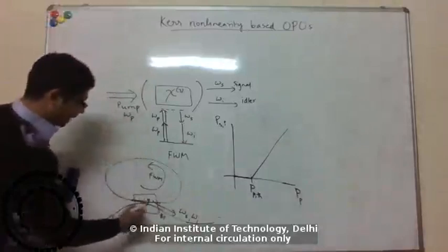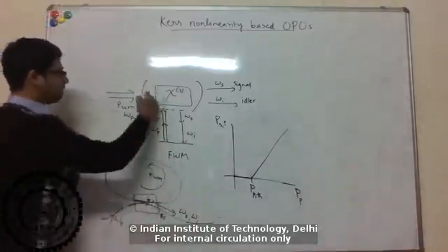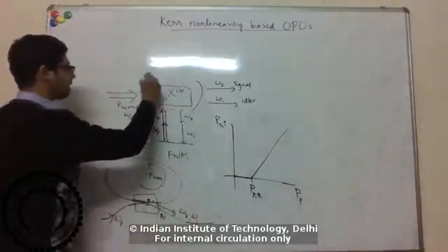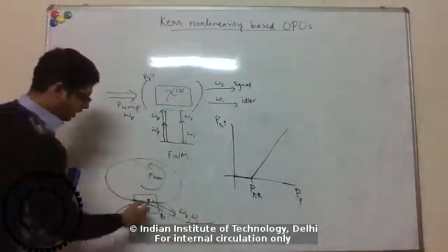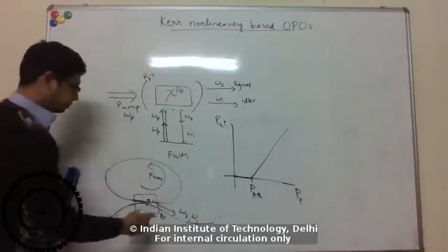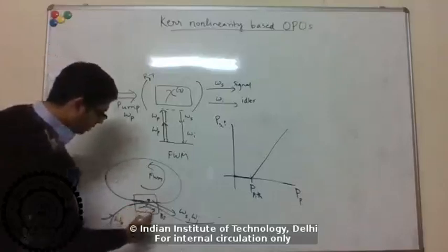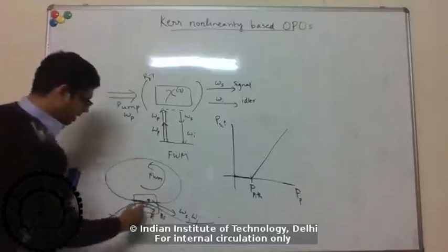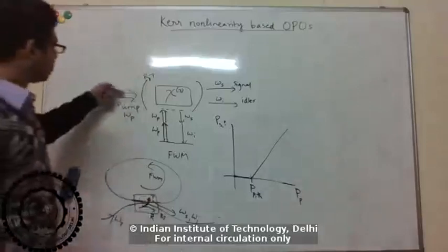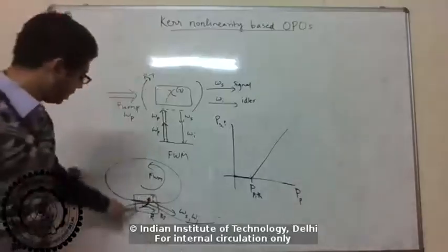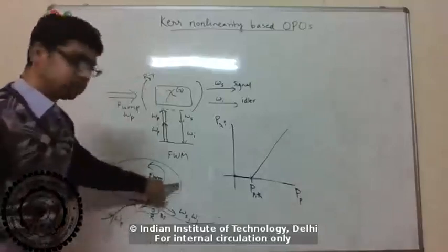So basically this coupler here is just like in a Fabry-Perot cavity, where you have some reflectivity and transmittivity for the mirrors. Here in the ring cavity, you can imagine the straight through port is like a reflection, and the coupling to the other port is like a transmission. The transmission is the one which gets from outside to inside the cavity, so that's the coupling from this coupling waveguide into the ring.